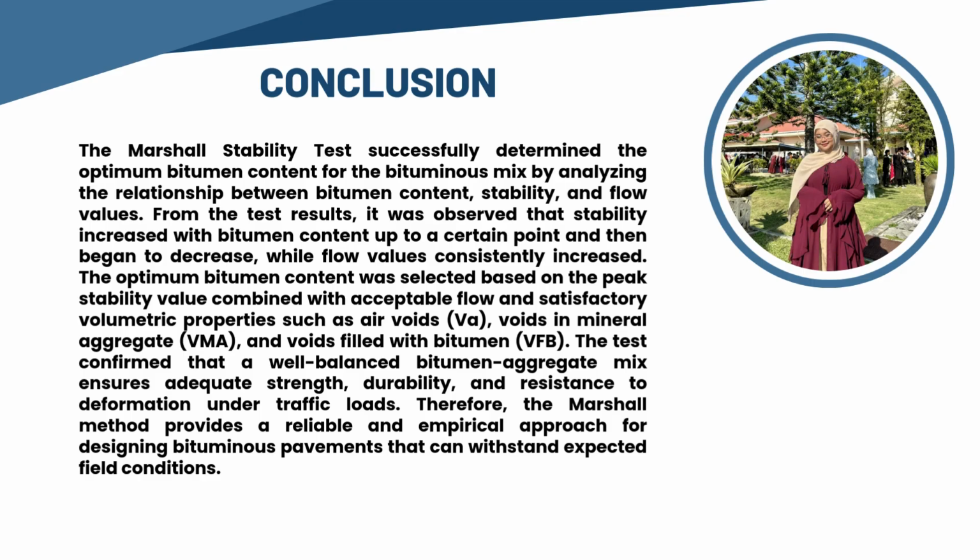The optimum bitumen content was selected based on the peak stability value combined with acceptable flow and satisfactory volumetric properties such as voids in mineral aggregate and voids filled with bitumen.